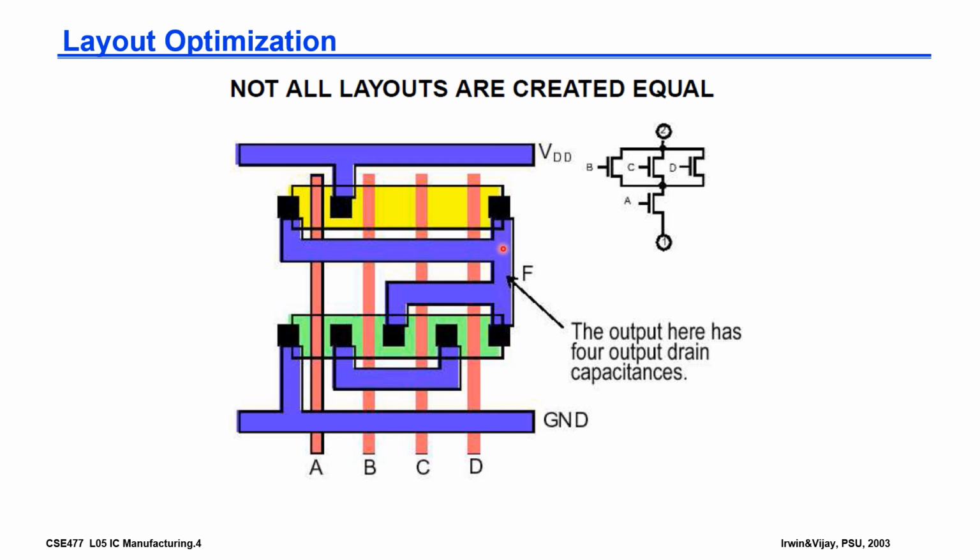And for the F side of PMOS here, the upper part there, you're going to have this in series, and this is PMOS. Why in series? Because you have a parallel at the NMOS, and the A side here is connected in, both are in series here, so you should have parallel at this PMOS side.